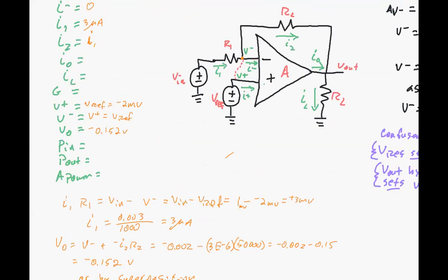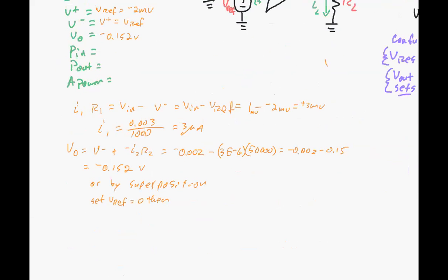If we set this voltage source to 0, then we've got the output that we know as V out A. It's minus R2 over R1 times Vn, which is 50 times Vn, and Vn is 0.001.